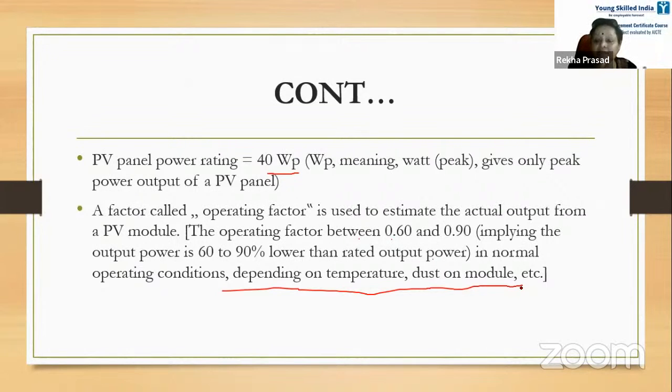First, you have to see how much you are going to produce. How many things will be connected to it? What will be the consumption of each? How many and what is the energy they'll be requiring? So you first calculate the total load, and from there you calculate the number of PV panels you will be requiring to produce that load.